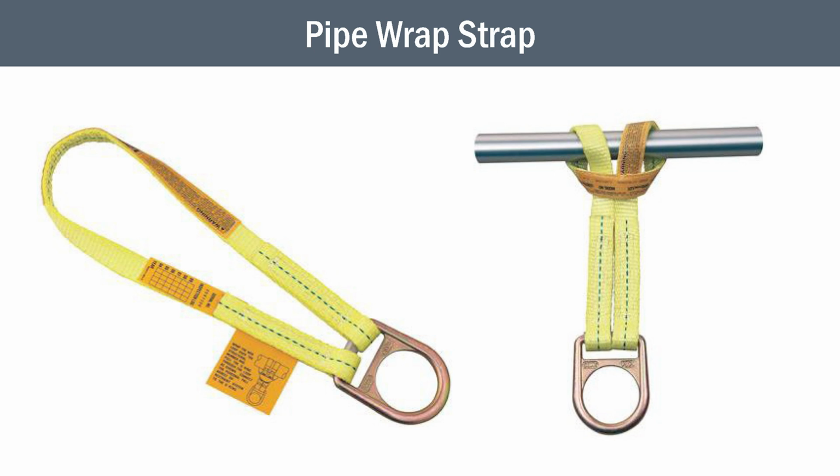One thing about using these straps, you've got a tie-off point, but don't you notice something? The one on the right is connected to, let's call it a steel pipe. Will that steel pipe hold 5,000 pounds? You have to look and make a decision. Where are my compatible tie-off points?